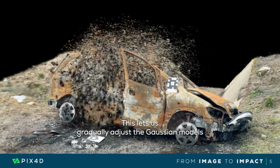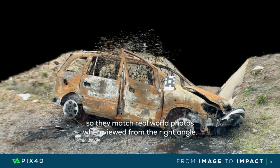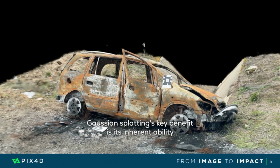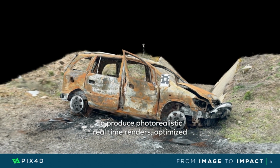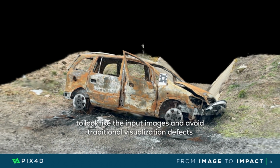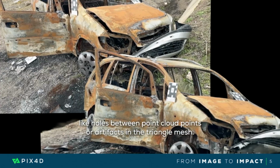This lets us gradually adjust the Gaussian models so they match real-world photos when viewed from the right angle. Gaussian splatting's key benefit is its inherent ability to produce photorealistic real-time renders, optimized to look like the input images, and avoid traditional visualization defects like holes between point cloud points or artifacts in the triangle mesh.